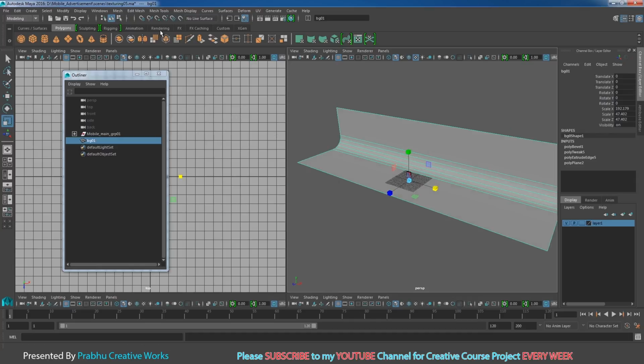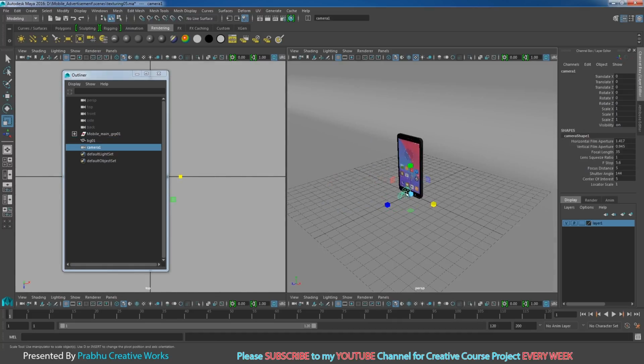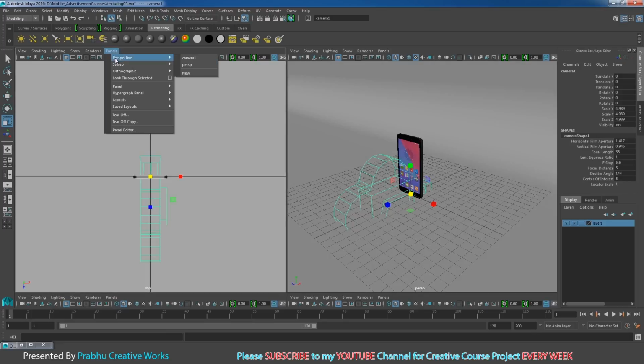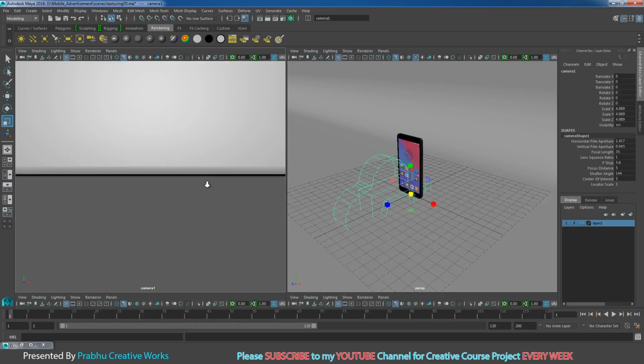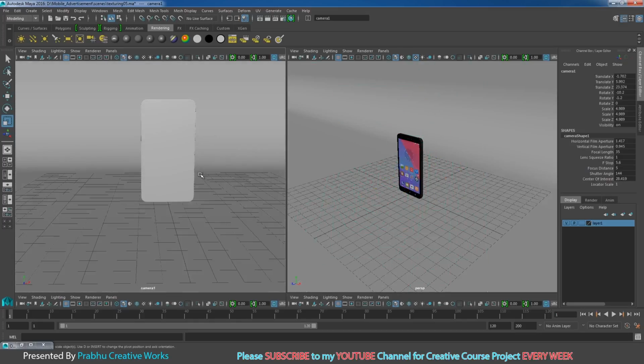Before that, go to rendering and click on create camera. It will automatically be created in the center of the grid. I want to scale this one very big. Now I will minimize my outliner. Go to panels, perspective and choose camera 1. Now you want to navigate this one. That means your camera view will be set.